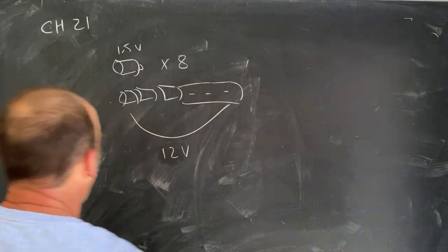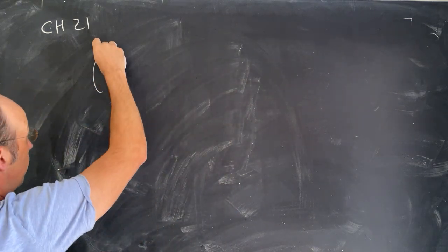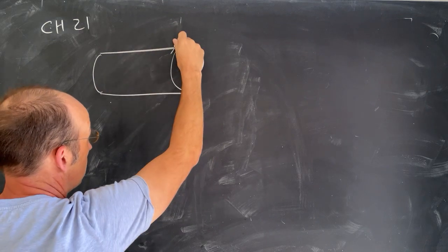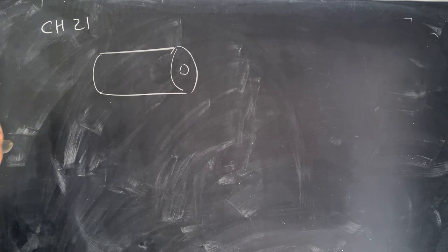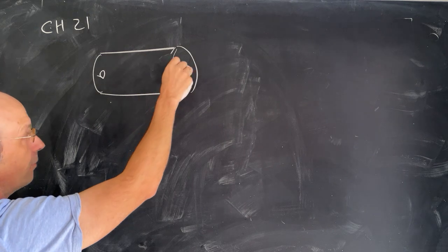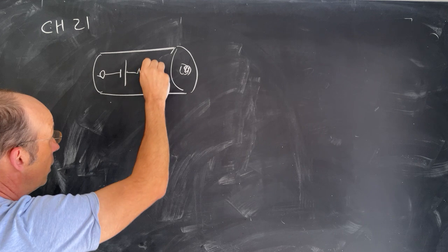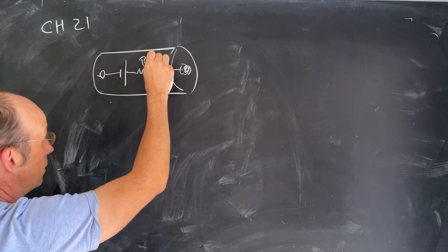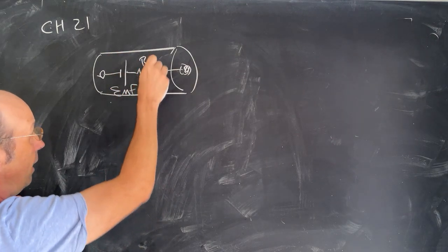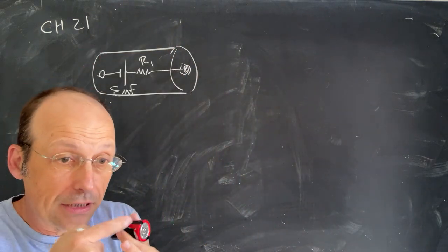But why? Well, we can model an actual battery with the following. So here's my battery. There's my D-cell battery. So inside we have terminals. Let's see, that's the positive side. So that's my positive terminal of the battery, and that's my negative. But there's also what we call an internal resistance. I'll call it Ri. The book uses this lowercase r. So this is EMF, and that's Ri. So we can model this actual battery as having a little resistor inside of there.